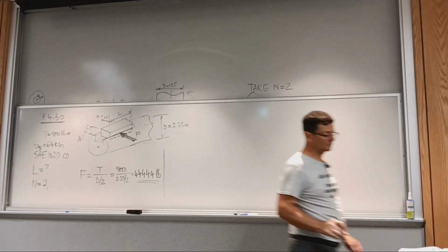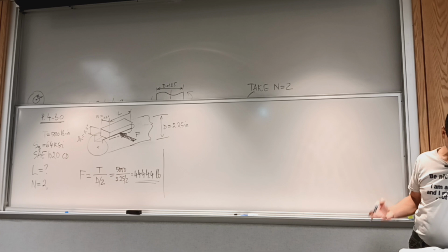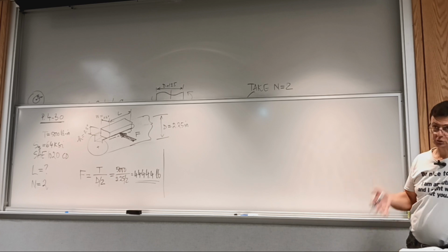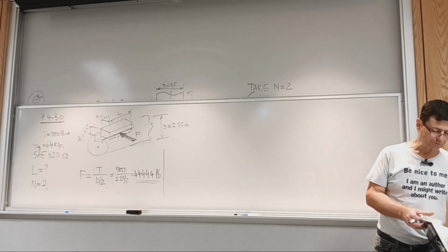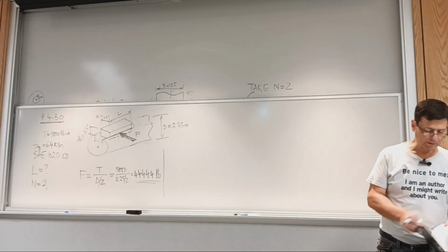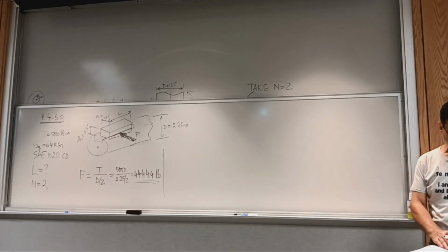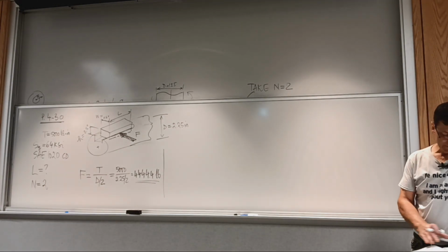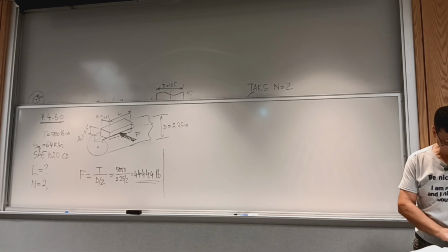Do we have any information about how the torque is transmitted? Well, it says a factor of safety of 2, so it's assumed steady loading, steady torque. So rather than searching through tables in the book, we go where mechanical properties of materials end, and we have the design shear stress for direct shear and for torsional shear stress.